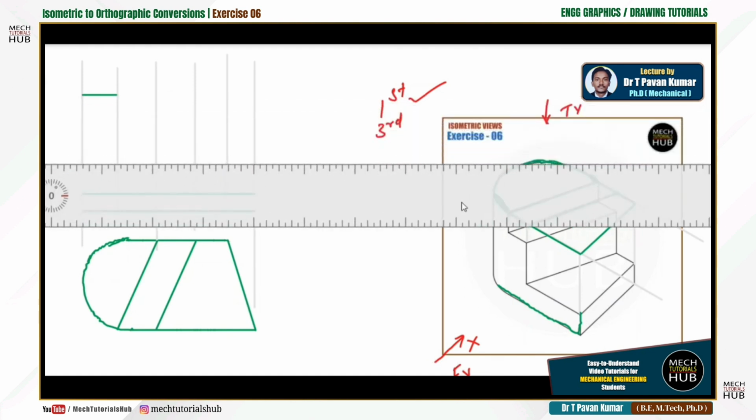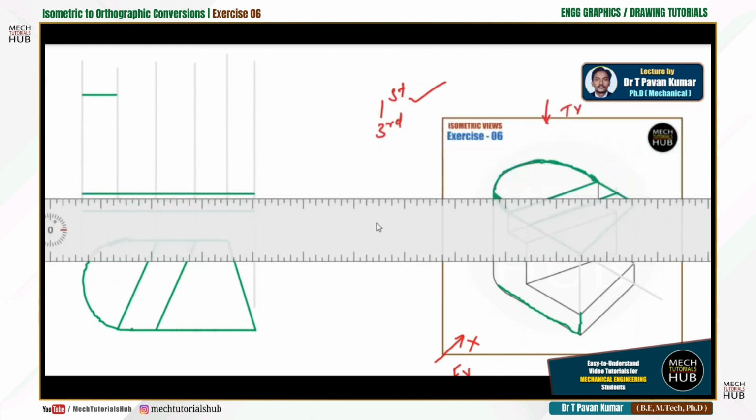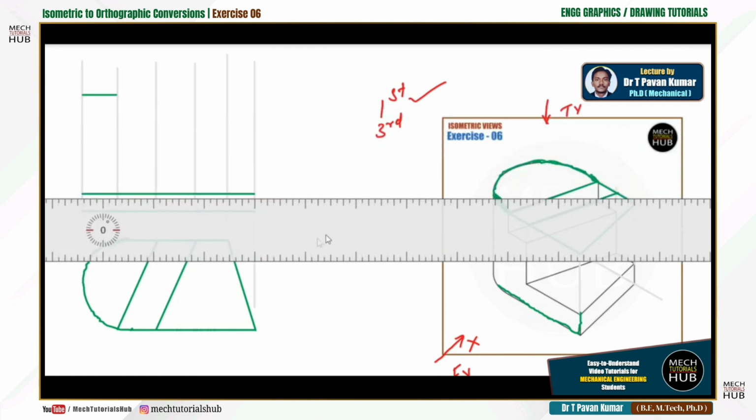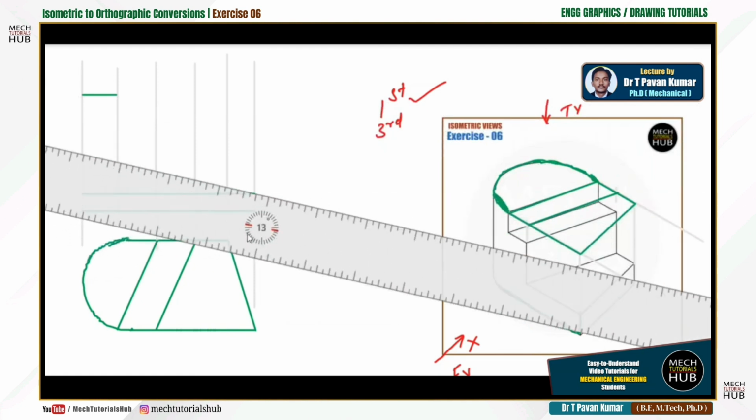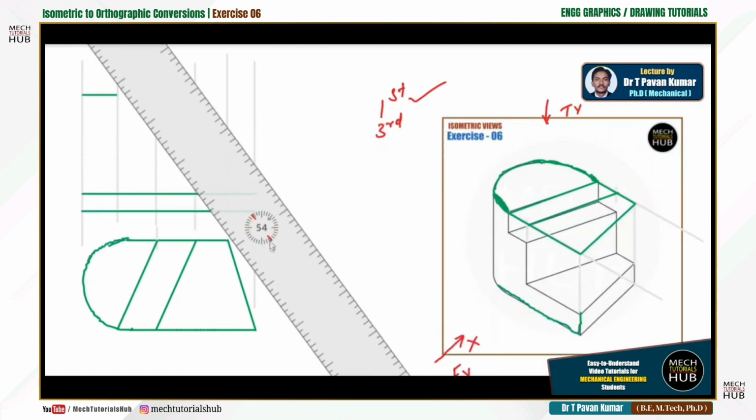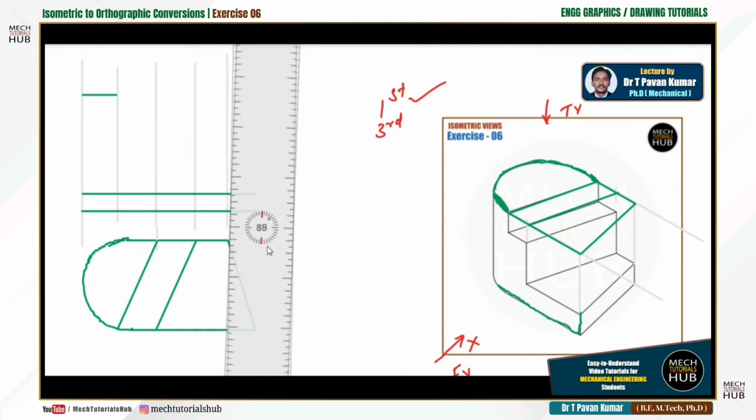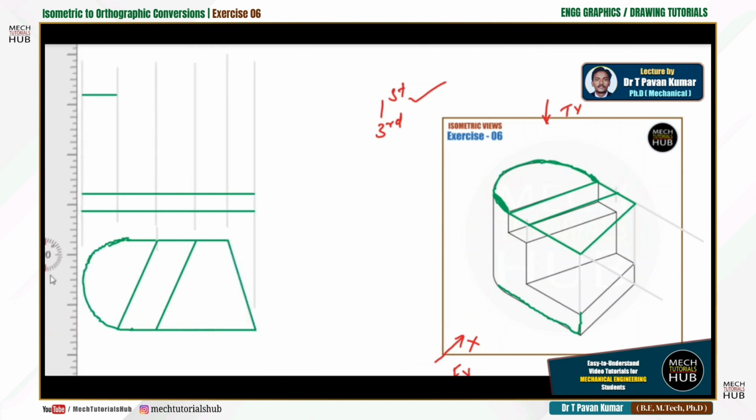Try to understand these two points which are important again. Here, why we have drawn the projector lines or extension lines, you just need to understand now at least, because those are helping us to drop horizontals, from where to which point we need to draw. That is easy. Now this 110 I have drawn, and as I said in the beginning, this point is not at all coinciding with the point on the other side of the component.